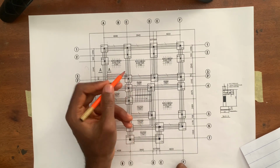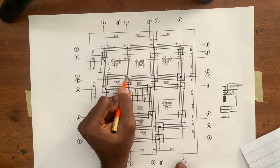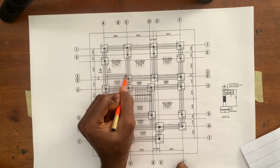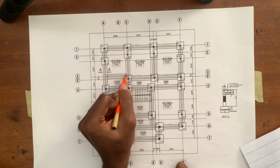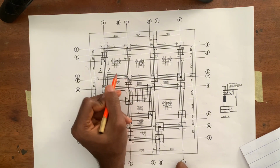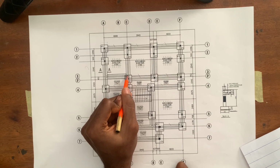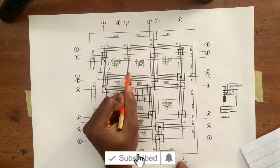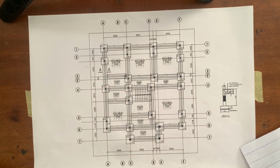Then if we look at this, we want to do this in such a way that we make the trench a regular rectangle and then minus this extra that has already been catered for when we're measuring our column pit excavation. So the distance of the trench we're going to be needing is the distance from this edge down to this edge. Since we know that call out C is at this midpoint, we can now minus half of the width of this trench to get us to this point. I hope that's easily understood.